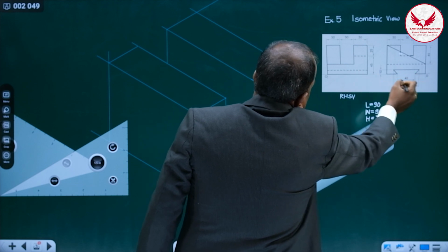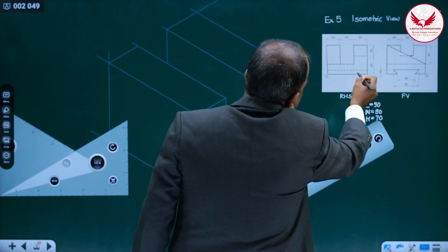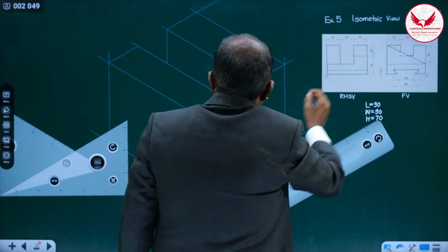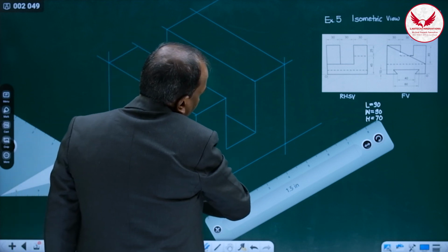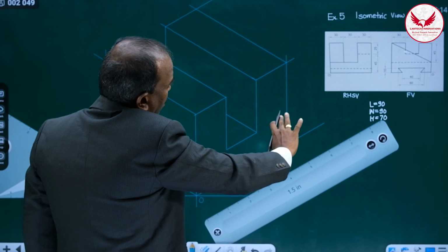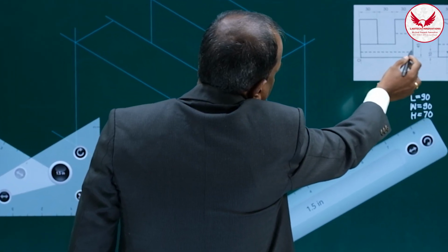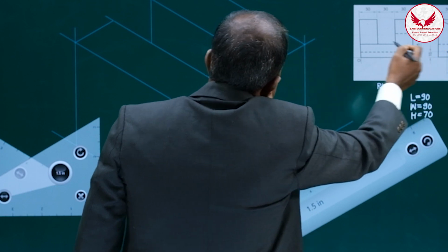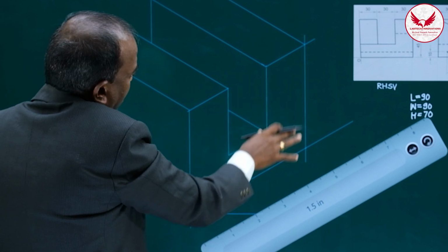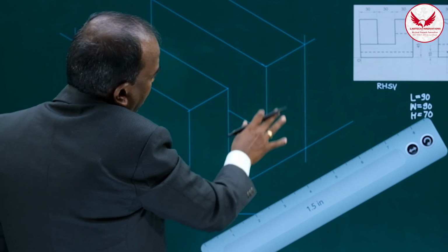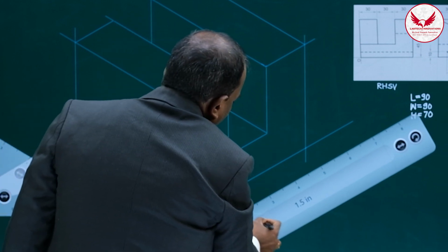So this trapezoidal slot in the front view and its dotted line throughout means here we'll get the trapezoidal slot, and whatever that slot is there, it is throughout. This dotted line indicates that on this frontal surface in the side view, that portion we will directly make dark.